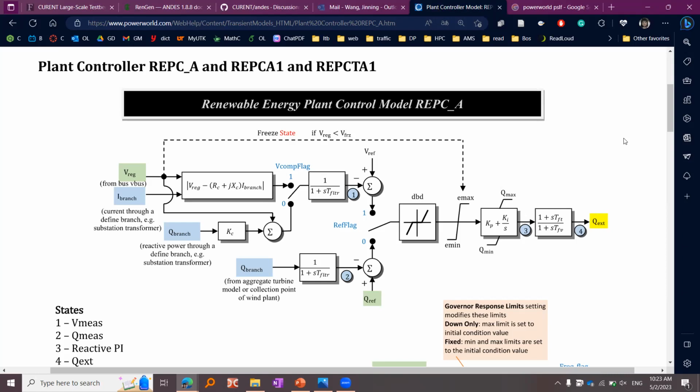So you don't have to do the switching behavior in this model. You can treat it as a conventional generator or something. So here we made the simplification, and there are many other models. They follow the same philosophy to do the simplification. This is a way before we can do the full-scale EMT simulation. We are using this way to do the renewable penetration study in the transmission grid.